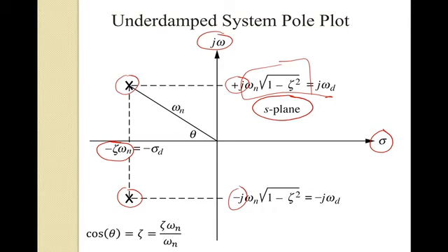So that is the representation of them, but I want to dig in a little bit further here, and as we start to interpret this S-plane and the pole locations, show you how that relates to the previous module when we talk about things like overshoot, peak time, settling time, and things like that.